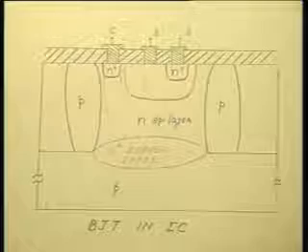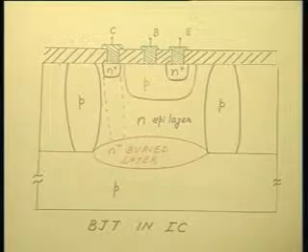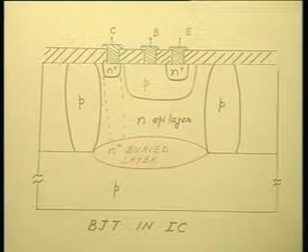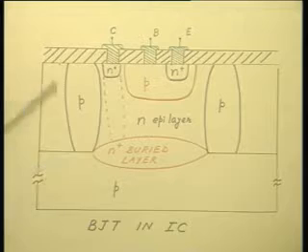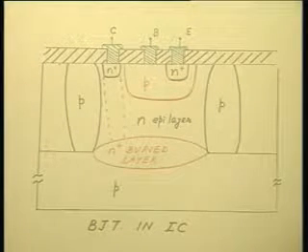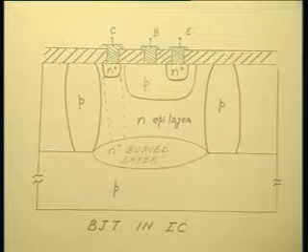So, all parasitic capacitances will have adverse effect on the speed of the transistor. And if you have this junction isolation, then you have a large junction capacitance associated with the collector N and isolation P. The PN junction capacitance will tell adversely on the speed of the transistor.